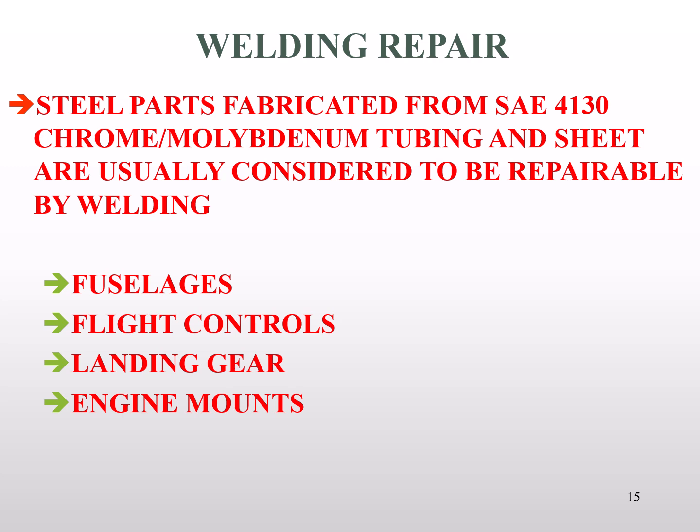The most common steel alloy used in aviation is 4130 chrome moly tubing and sheet material. It is a very weldable steel. It's also a very high strength to weight steel, so therefore we can use lighter parts and still achieve the strength required. So typically steel parts manufactured from 4130 chrome moly steel are weldable. This is also an FAA question that comes up. What is the most common alloy of steel used? SAE 4130 would be your answer.